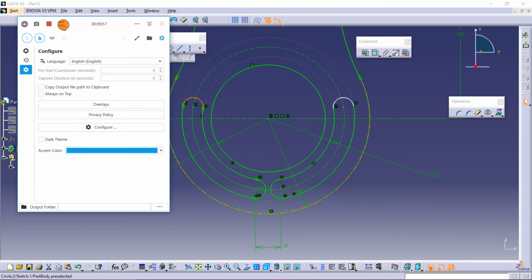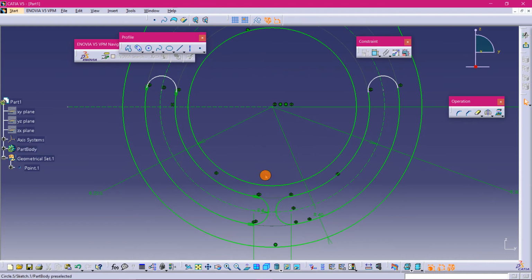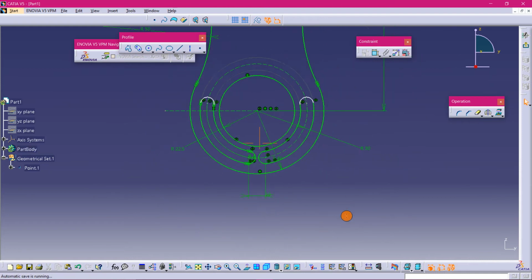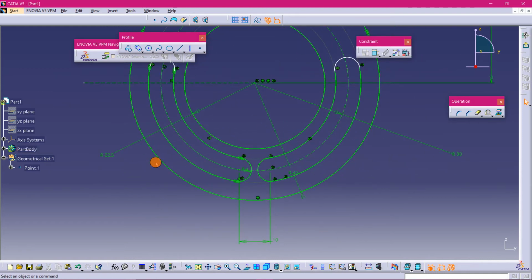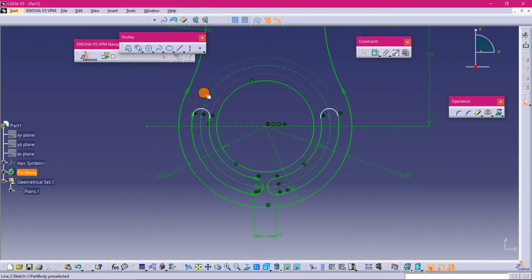Since the sketch is intersecting, just reduce the radius to 4 mm, because in drafting they didn't detail how much this dimension is. So you have to assume that accordingly. So again, this part is below the axis line, so just drag it, and we need one more circularly elongated hole here. So I'm selecting the center,